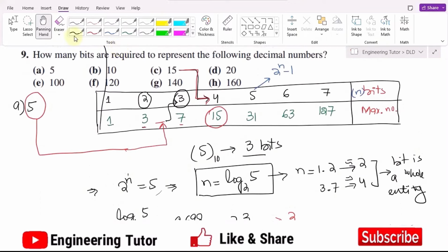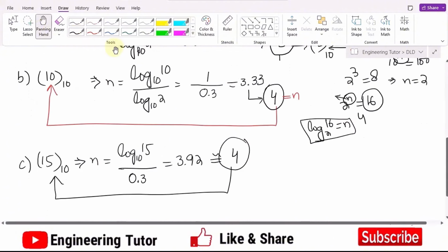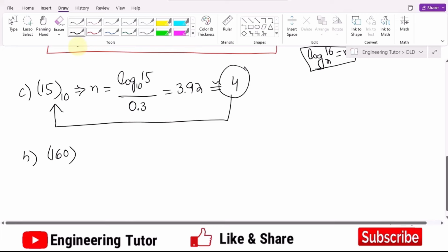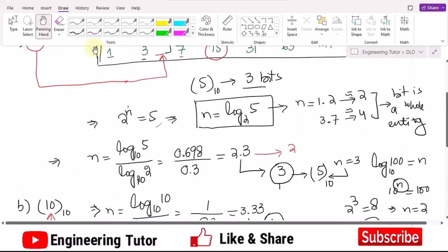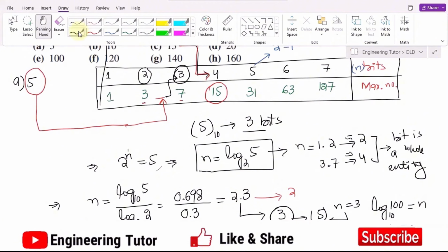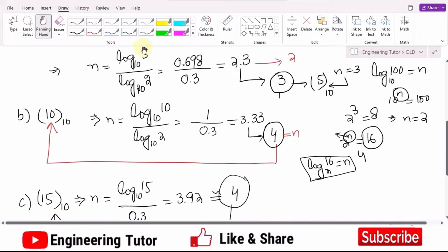Now let me pick this H, and H is 160 decimal. How many bits should I have to represent this one? Let me use the same formulation. With 7 bits the maximum number I can get is 127, and with 8 bits the maximum number I will get would be 255. So it lies in between them. I have told you that if the range is known, the lower number and the highest number within which the number can lie, I have to pick the higher number. So 8 bits can be used to represent this 160. So 8 bits will be used.